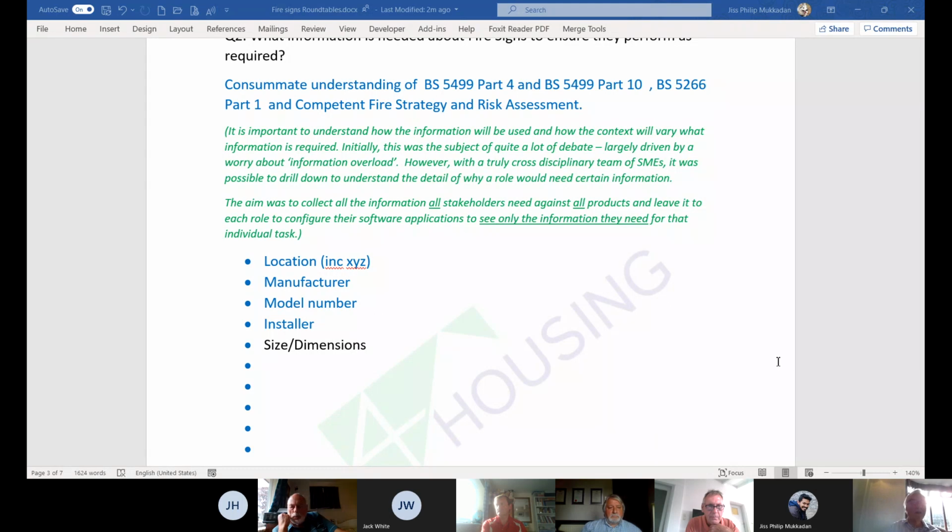Yeah. Just one point on this. What happens when the building actually changes? So within the sizes of the signs, one of the other bits is the cosine of the angle that you're looking at the sign. So if the escape route within a bigger open area changes, then effectively the sign size ought to change on a new installation.